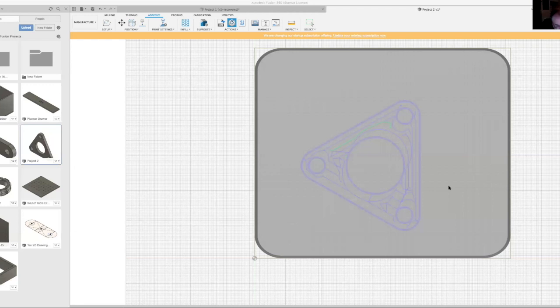The one thing that I don't like about the current Fusion slicer is it's a little slow, and the edge detail on real sharp edges isn't as smooth as the Prusa's is. But the neat thing I use it for is you're gonna whip together a little bracket. I use it for a lot of fittings in the shop to go from one dust hose to another. You can whip out a fitting with a revolve command, and I use the shell command that Tim showed us tonight. You can whip out a fitting and then print it out. You can do the whole thing, design it, slice it, and print it all in about 2 hours. And then I have a fitting for out in the shop.